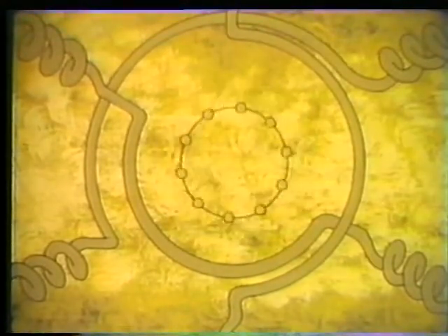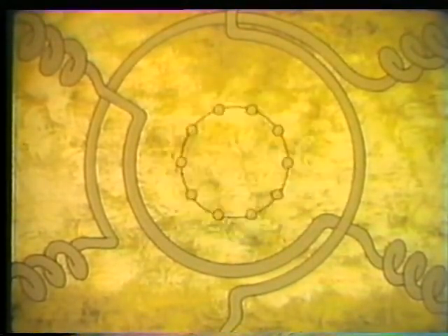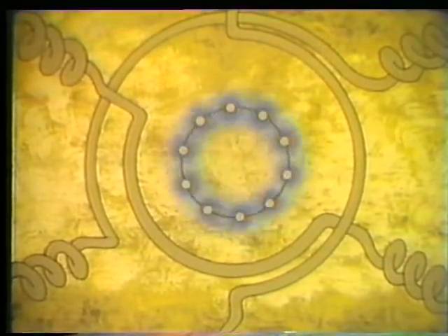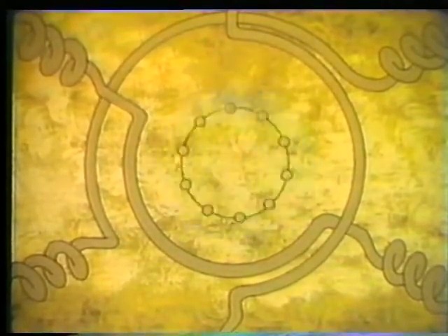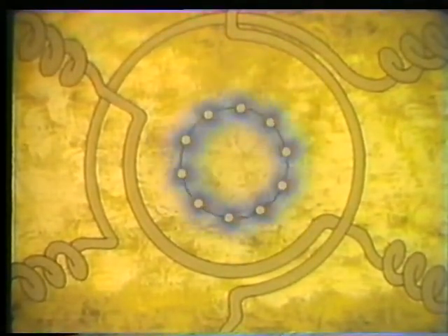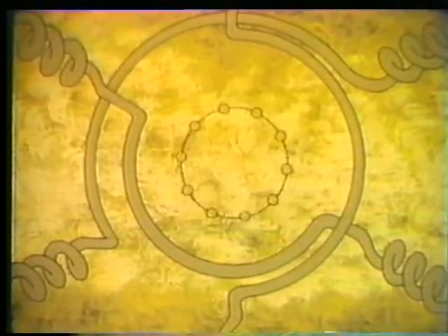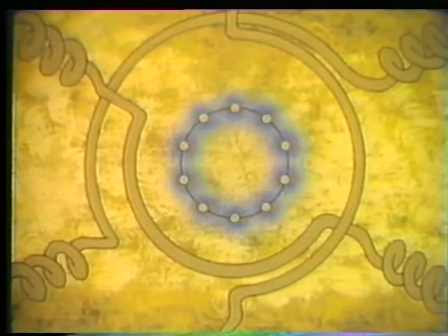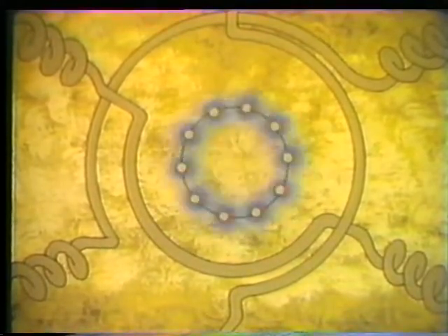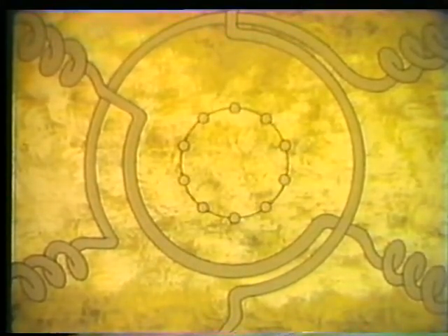The pulsation of the rotor's magnetic field causes relative motion between it and the stator coils. The stator coils are conductors, so once again there's relative motion between a conductor and a magnetic field. Because of this relative motion, voltage is induced in the stator by the rotor. This voltage increases the effective voltage in the stator.